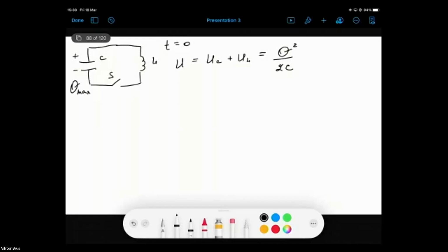This stands for the energy accumulated in the capacitor based on its accumulated electric charge at this given moment of time, and its capacitance. And also plus 1/2 L times I squared. So also in this moment of time it depends on the electric current which flows through the circuit and the inductance of the electrical circuit.